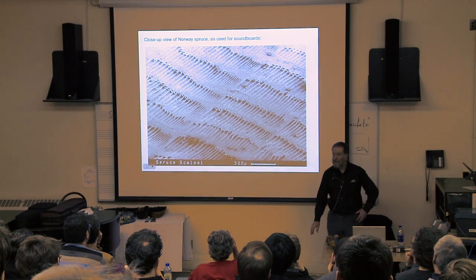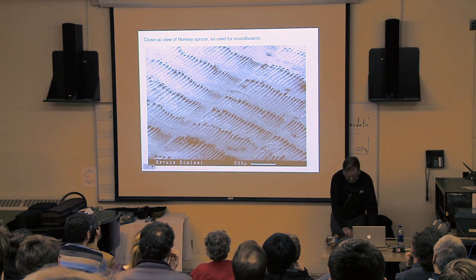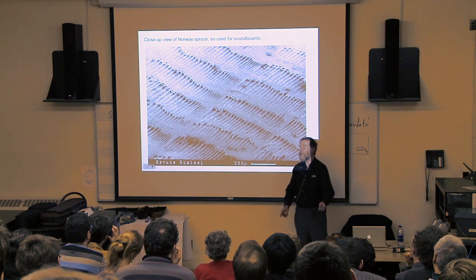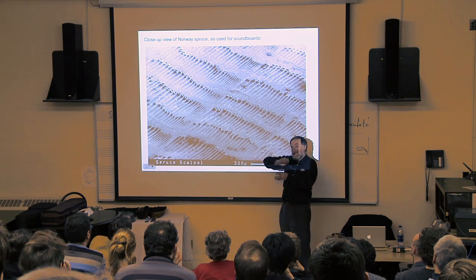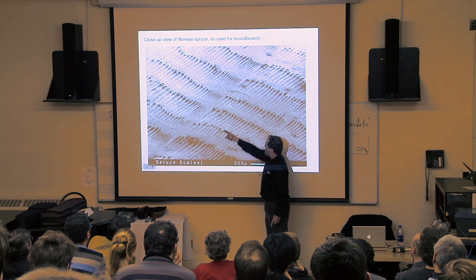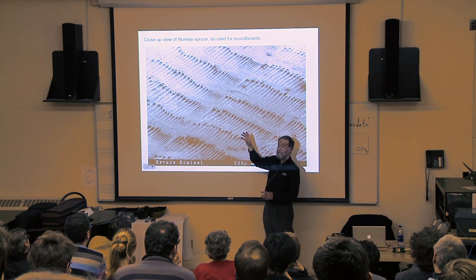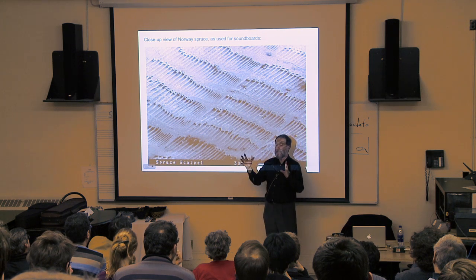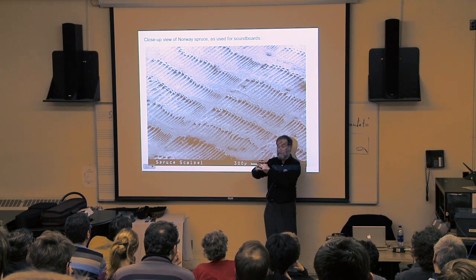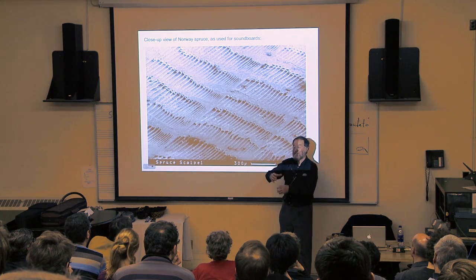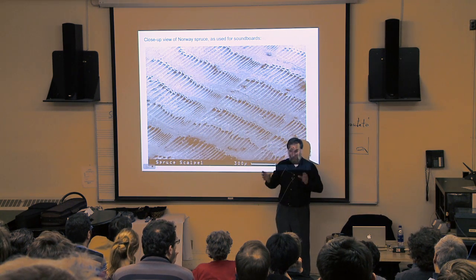Why is wood so good? Well, here's an electron microscope picture of a piece of instrument quality spruce. So this is a little piece at the top of this violin here, say, which has been cut with a rather sharp knife, almost exactly parallel to the grains. And what you're seeing here, you see the individual wood cells looking like tubes. And the structure of this wood is like a box of drinking straws, basically. Each wood cell is a thin-walled tube. They're squarish drinking straws, but with a lot of empty space inside, and they're all stacked together. That sounds like running a bit of glue down your box of drinking straws.